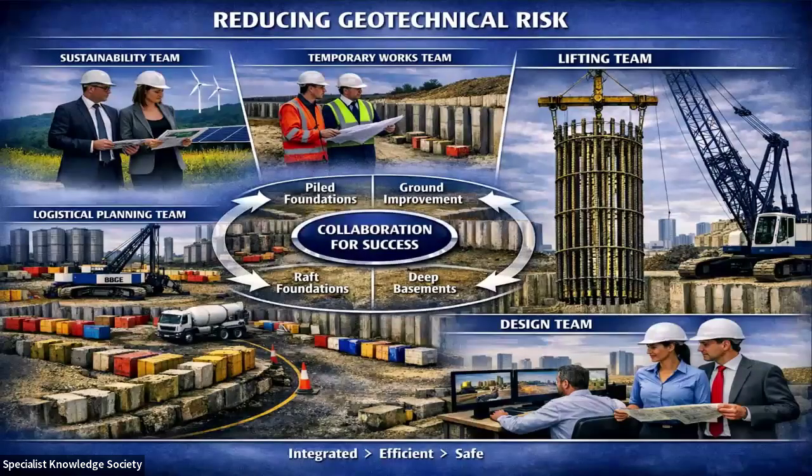We've got what I've termed the lifting team there. The lifting team is quite a broad term. It's any kind of lifting that's taken on around foundation construction. So you can have piles as we move on to, or foundations which are manufactured off-site and brought into site. Again, you've got to consider how they're lifted into place once they get to site. Or you may have a lot of stuff fabricated actually on-site that needs to be lifted and put into position. So how those things are lifted and actually constructed is a significant input into how the right foundation solution is taken.